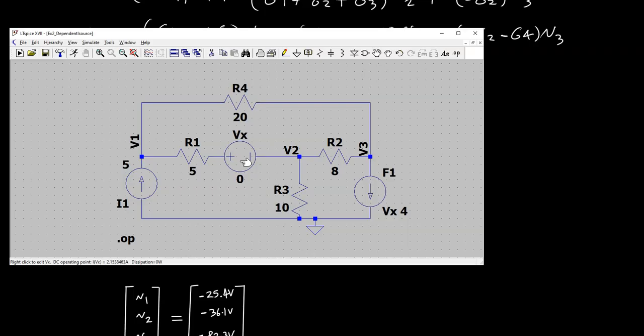I'm actually injecting a dependent or an independent current source value into that branch, and so that wouldn't work. Any value, if it's 0, is going to open my circuit, because 0 current through a current source means that it's an open circuit. And if I have any non-zero value, I'm actually injecting current into my circuit and messing up the operating point of my circuit.